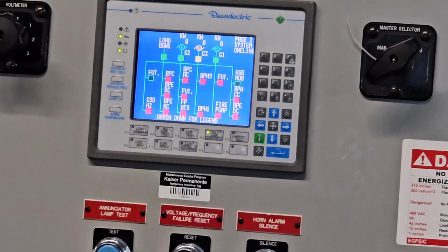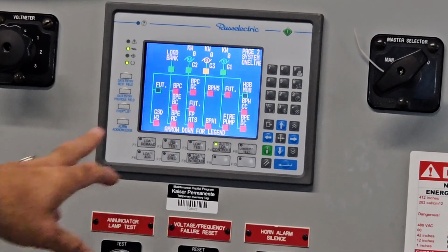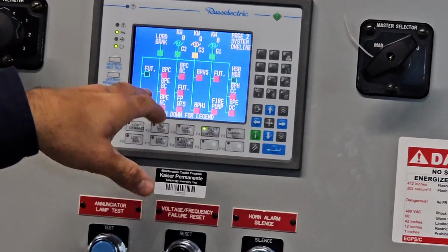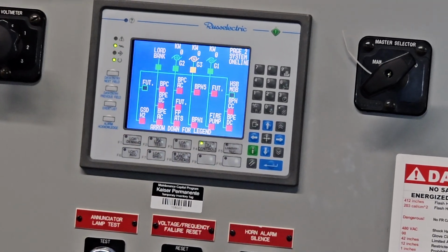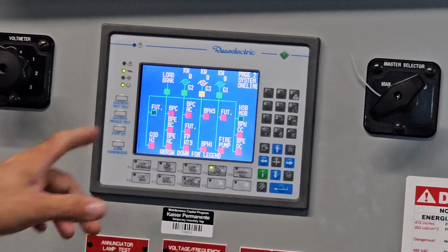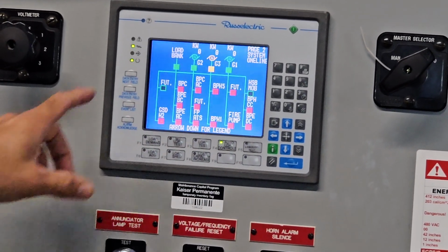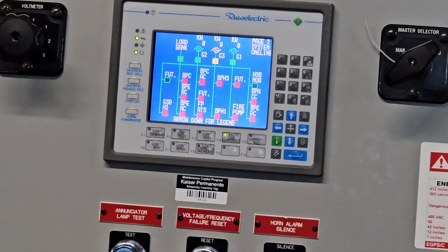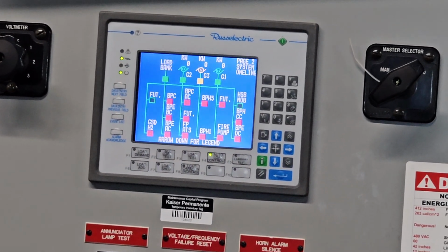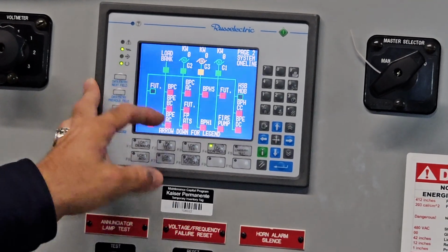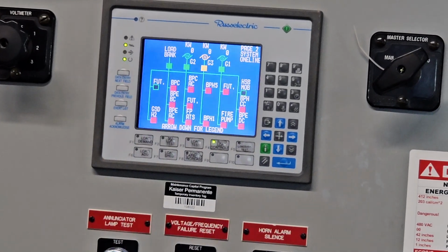We have this filter breaker racked out, right? And then the rest of them are normally closed. And then the generator breakers, they're normally open. So when the generators are running, the breaker closes, the bus gets energized, it will turn to red. Red also means that it's energized for busing. For breakers, it means it's closed. And then the breakers will turn red.